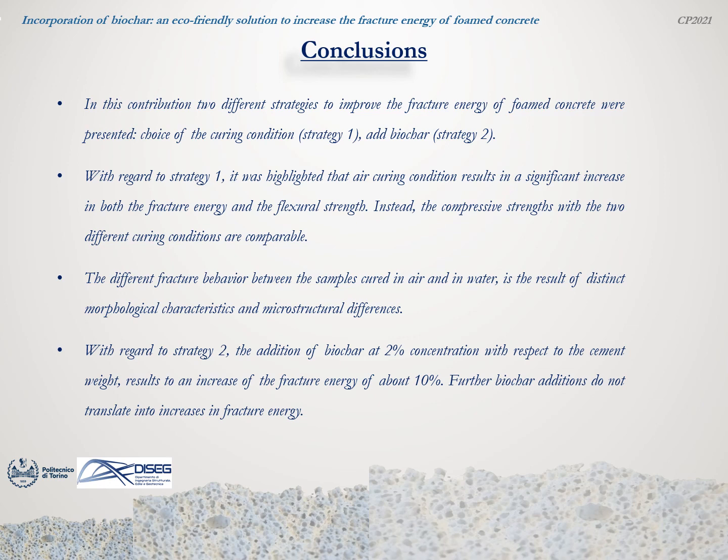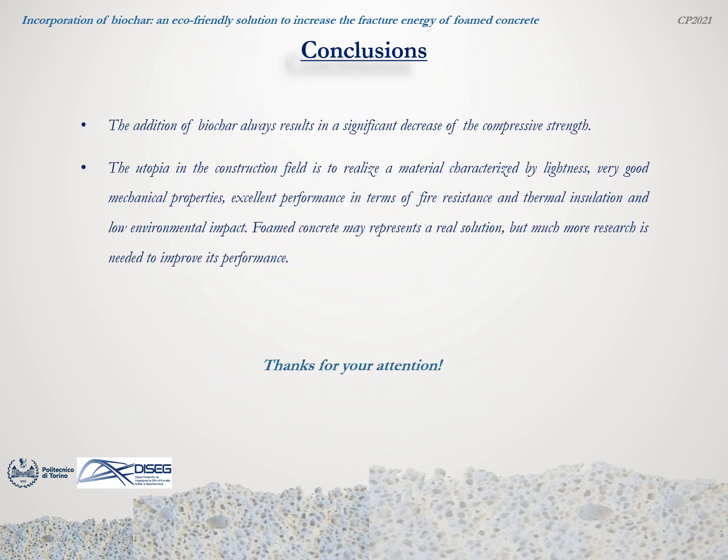With regard to strategy 2, the addition of biochar at 2% concentration with respect to the cement weight results in an increase of the fracture energy of about 10%. Further biochar additions do not translate into increases in fracture energy. Moreover, the addition of biochar always results in a significant decrease of the compressive strength. The utopia in the construction field is to realize a material characterized by lightness, very good mechanical properties, excellent performance in terms of fire resistance and thermal insulation, and low environmental impact. Foamed concrete may represent a real solution, but much more research is needed to improve its performance.